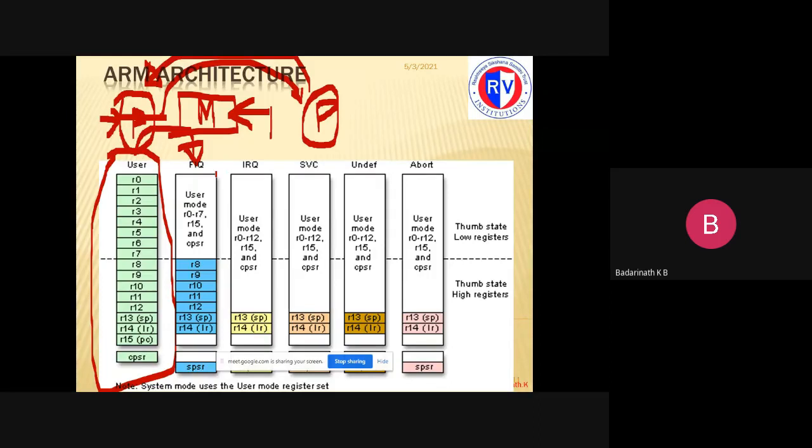But they thought that implementing registers inside the controller or the core is a very costly affair, because it is a flip-flop. Every bit is implemented with a flip-flop, as you studied in digital electronics last semester. Every flip-flop requires so many gates, yes or no? One flip-flop is required for one bit of storage in a register, so one flip-flop consumes a lot. That is why, the more registers, the more the cost of the chip, the larger the size, and the higher the power consumption.